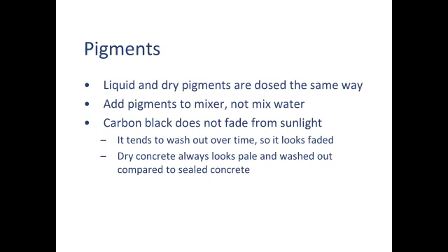I had mentioned that I dose them the same way, liquids and dries. Always add your pigments to your mixer. Never add them to the mix water. This is a context thing. If you have a bucket of mixed water that's carefully weighed out, exactly the amount of water you need, and you add your pigments to the water, the pigments are going to settle to the bottom of the bucket. Even if you stir it, there's still going to be some pigment in the bottom, because it's not like you're adding grape Kool-Aid to the water and it dissolves.